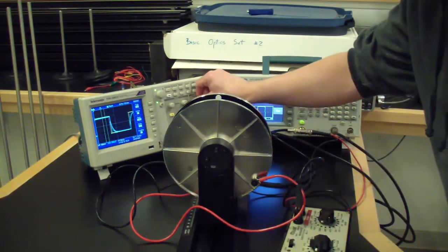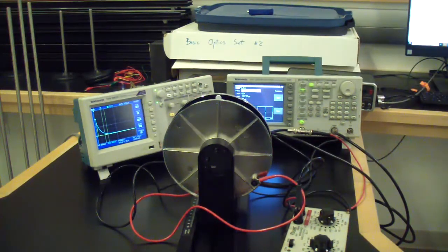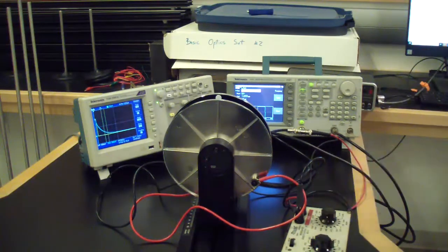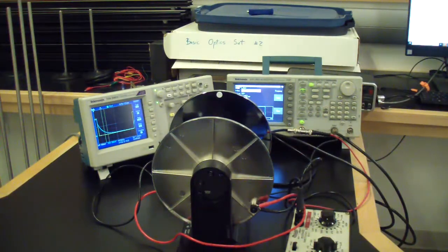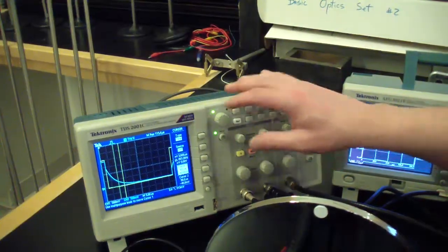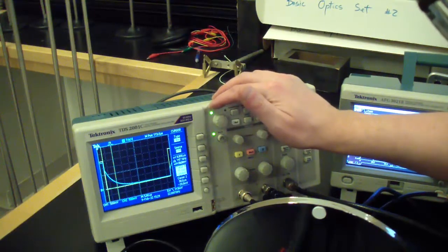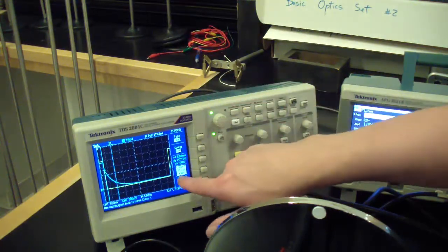Position your signal conveniently on the oscilloscope. Choose a resistance on your resistor box that will let you see the exponential decay curve even if the plates aren't very close together. Separate the plates by about 10 centimeters so that we can measure the parasitic capacitance in the system. Using the cursor function on the oscilloscope, measure the voltage on the capacitor at the beginning of the exponential decay. Divide this value by E and record the result.